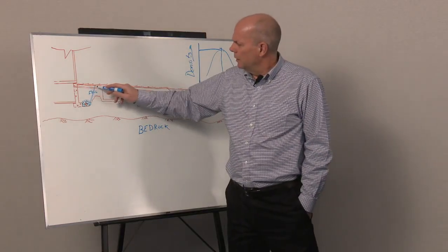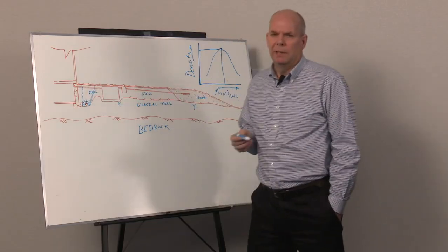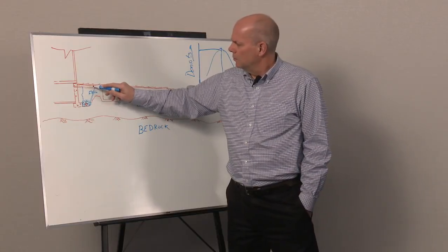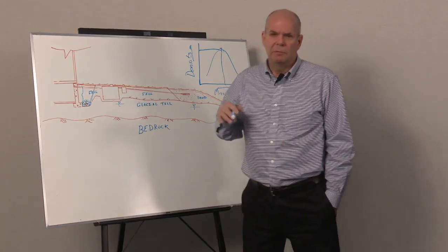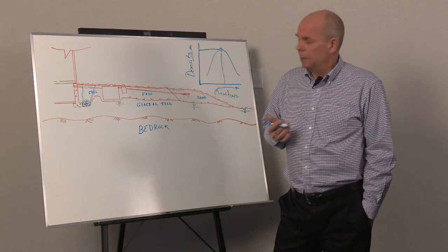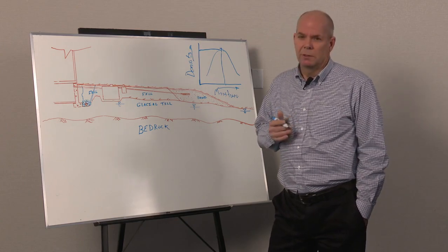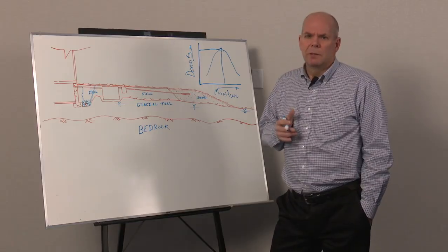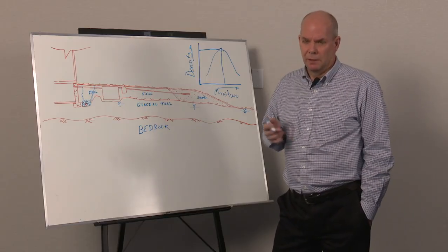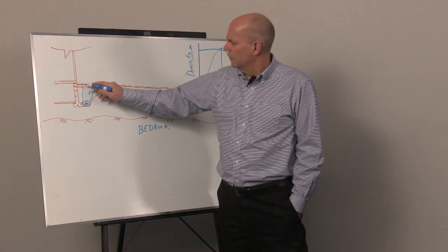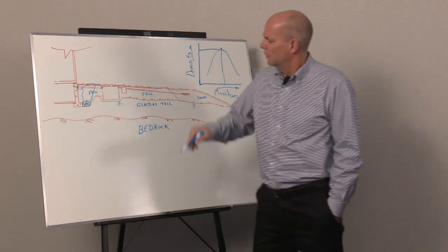Another issue you can have in between here is you get heat loss from the house that keeps material here from heaving in the frost. As you cross that, you get into material where the full 4 feet of frost develops and ground heave, particularly in the fine-grained soils that are clay-based tills again, or fills, and you can get maybe as much as 3 or 4 inches. Some of the real silty sands and materials like that, probably more in the Amherst area, are highly frost susceptible, and you can get 5-6 inches of differential movement. So in that case, your pipe can actually rise, and then it's fixed at the house, fixed there, and it can rise in between.